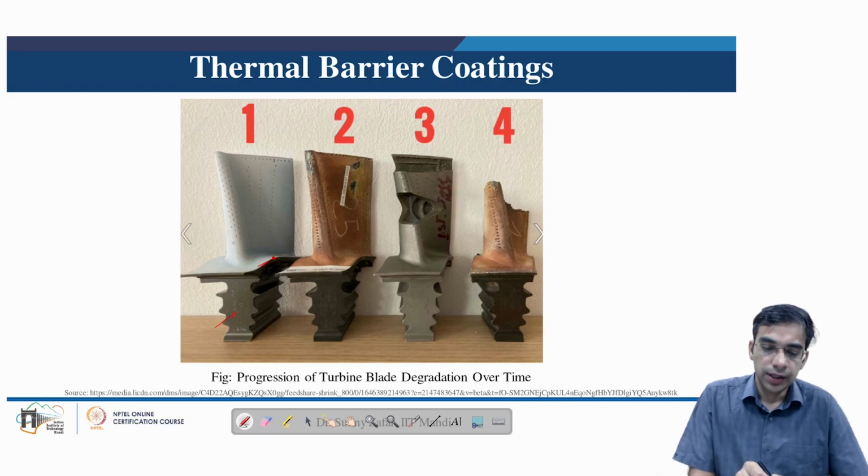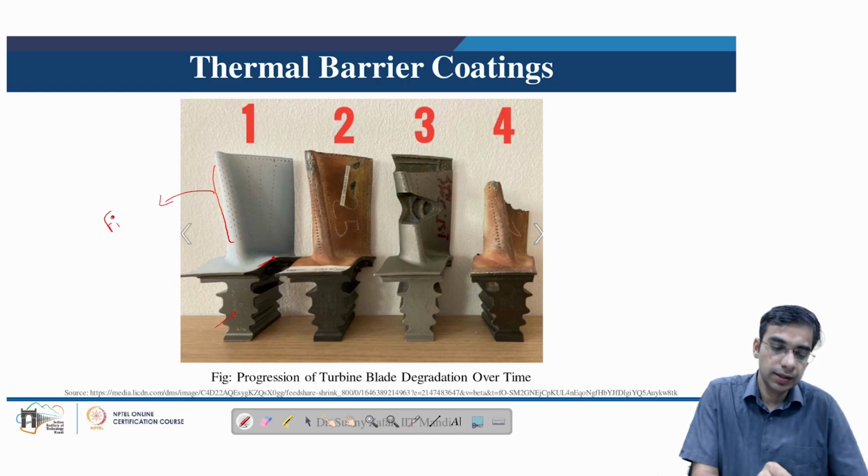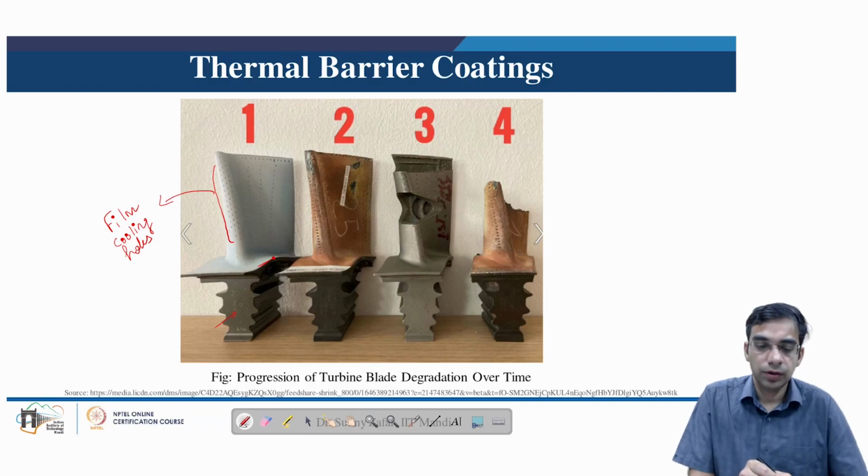And we can also see here the sequence or pattern of the film cooling holes here, as these are created using EDM or laser beam machining as discussed in the previous lessons. So these film cooling holes enhance the surface area of the blade for maximizing the heat transfer.